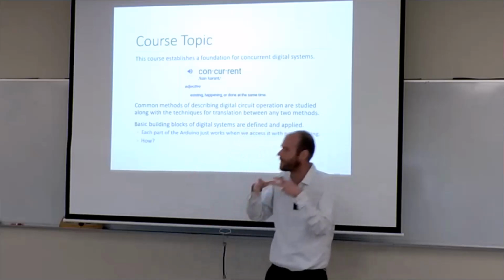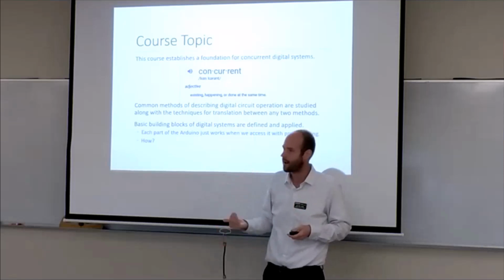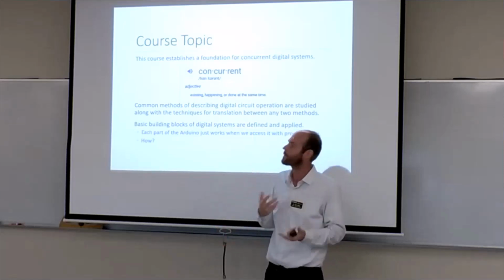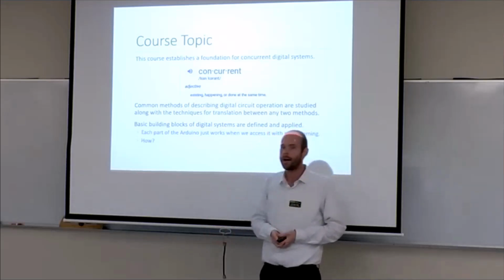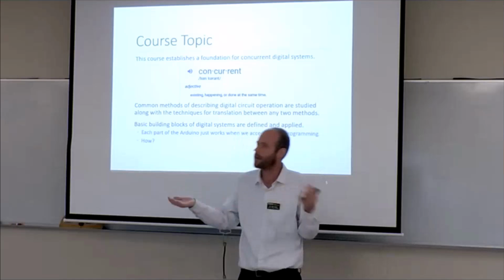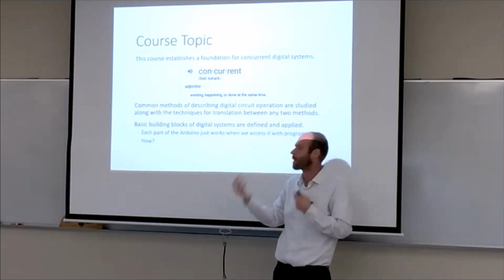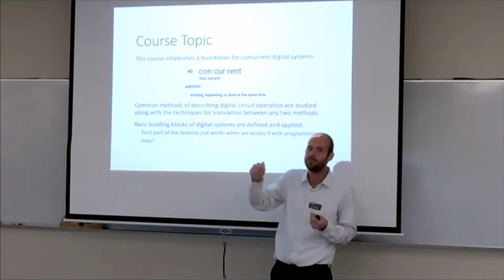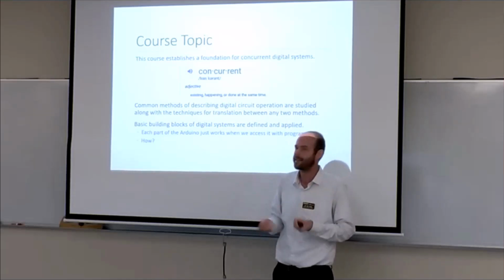The FPGA is a circuit. It's not a sequentially running piece of C software. So there are some key differences in what we are building and how it's working. And you may even remember from your earlier interfacing with buttons and stuff in 179, maybe your code, if you didn't program it to check the button enough, you miss a button press or it skips something. That is not a concurrent design.